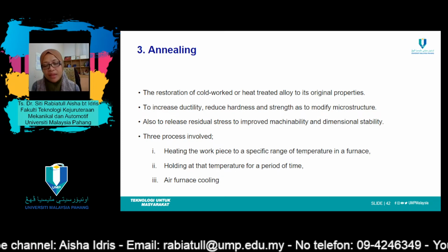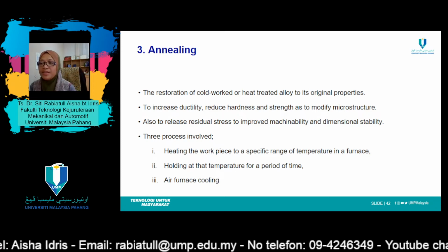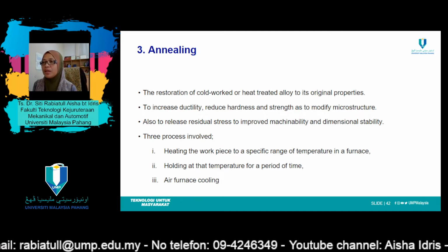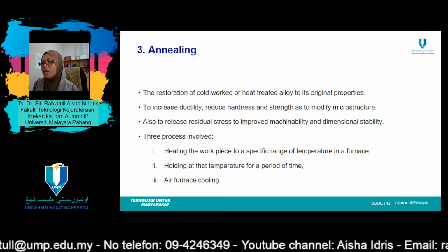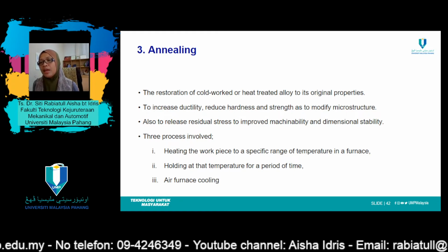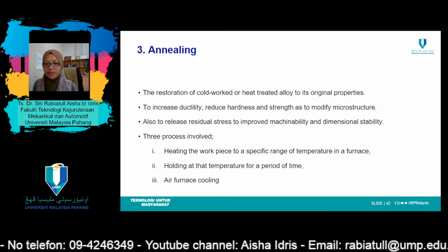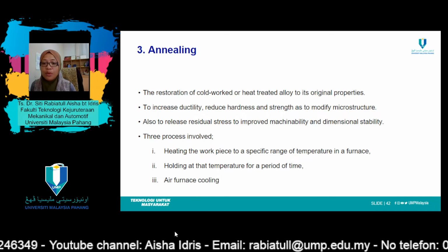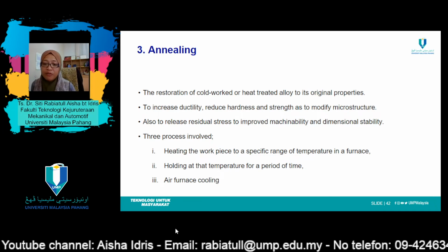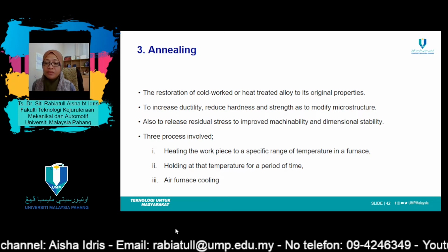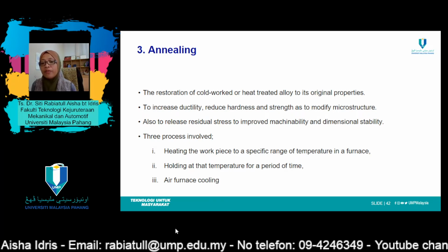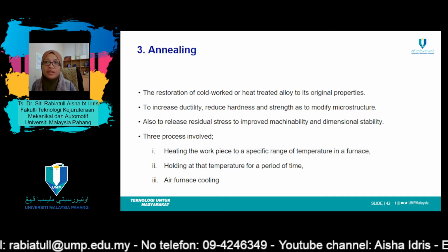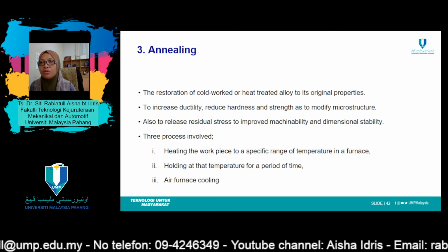Same thing for steel. After certain work or being heat treated, it will feel stress. So to reduce that stress, to gain its original properties, we will introduce the annealing process to it. Three processes are involved in annealing: heating the workpiece to a specific range of temperature in a furnace, holding that temperature for a certain period, and after that, furnace cooling. Put it in the furnace to slowly cool the temperature. I mean, let it cool together with the furnace.